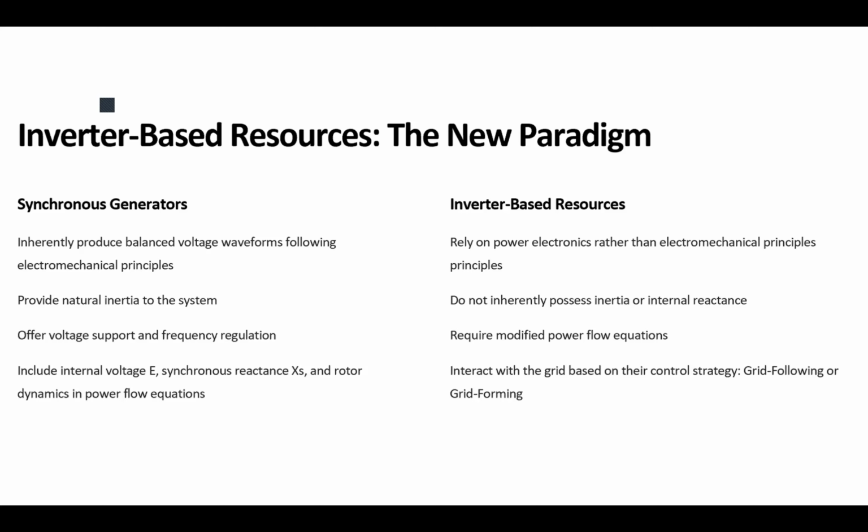So far we didn't add the effect of the IBR. Today, we are going to talk about what the IBR's effect on the power flow analysis would be, and how the difference between inverter-based resources and rotary machine-based resources would affect that analysis.